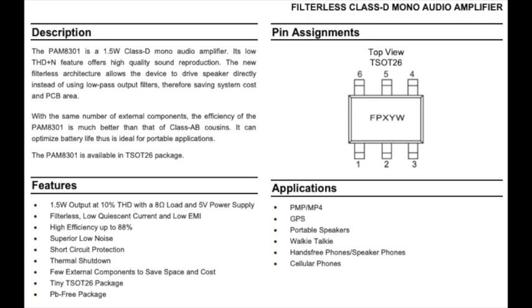Some notes from the third section: there are no dynamic characteristics, so it didn't get points for that, but that's okay. It doesn't necessarily need it. It is kind of lacking on the noise characteristics. I would have liked to see them built out a little bit more, but what they have is sufficient. The absolute maximum ratings include things like your maximum junction temperature, the reflow temperature and storage temperature, but that's all the thermal characteristics. It doesn't really show much else other than that, which is fine. We don't need much more than that to design with this part, but it could have been built out a little bit more. For its effort, this datasheet receives 65 points out of 90 in electrical characteristics.